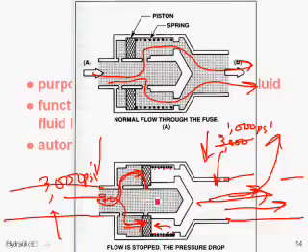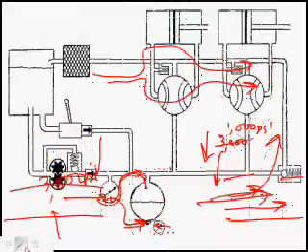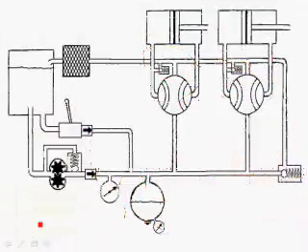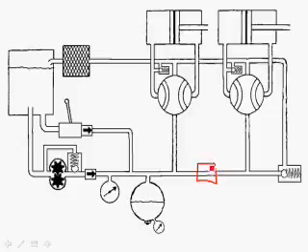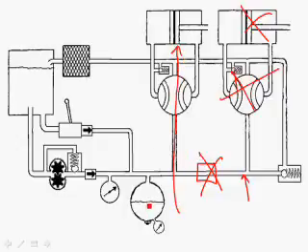So if you were going to pump all your fluid overboard anyway, nothing would work either downstream or upstream. So it's kind of nice to have hydraulic fuses in hydraulic systems. You might want to find out if your aircraft has hydraulic fuses. For instance, if we put a hydraulic fuse right here and we had a leak right here and this closed it off, this actuator and this selector valve wouldn't work anymore, but this one would still be good. I'll take 1 over 0 anytime.